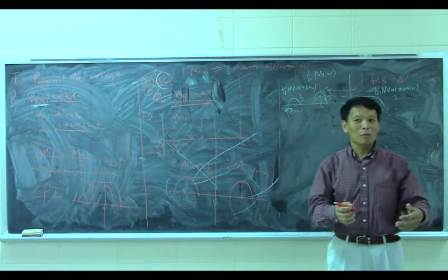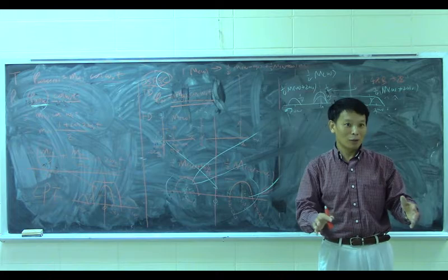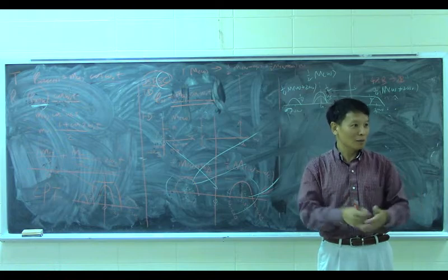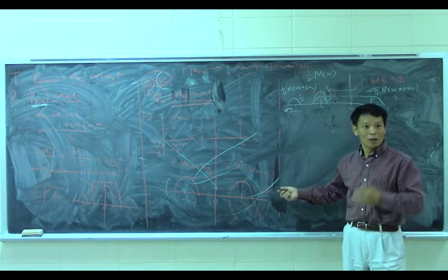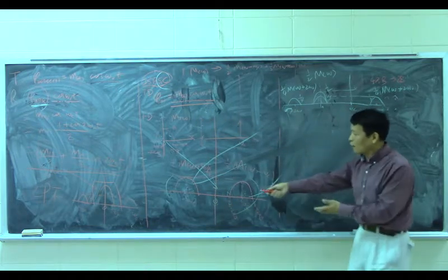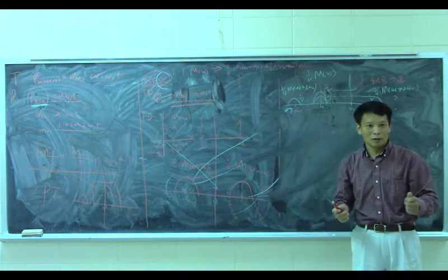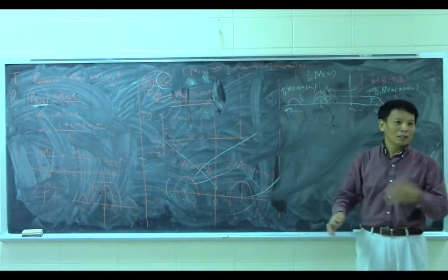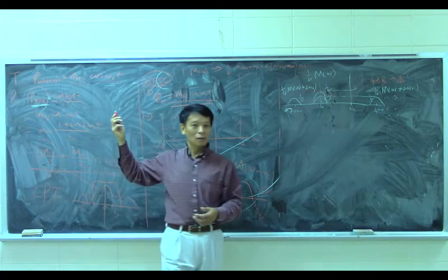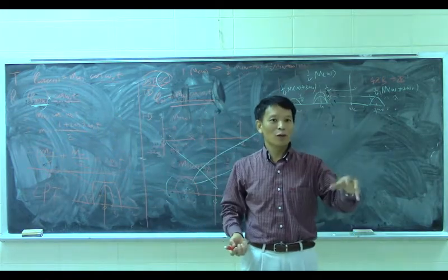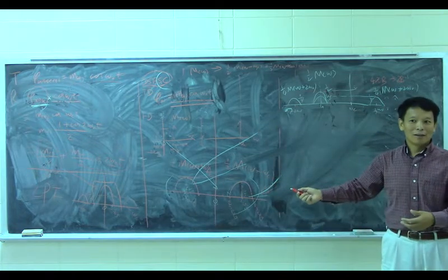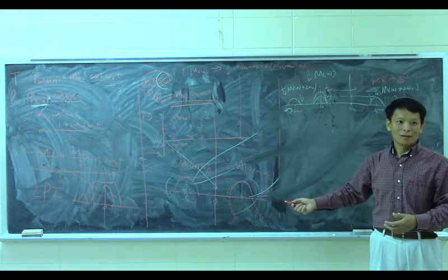Okay, the device we want to implement in lab is in time, right? In the time domain. You can only do this in time. We human beings live in time, right? So you can only do this in time. And we always focus on this is how you see this in time, this is how you see it in frequency. We are discussing here in frequency, shift this, shift that, on the left and right. All this translated in time is what? Multiplication. So if you have a multiplier, then you do this. So it shifts. So a multiplier can make you manipulate any frequency.